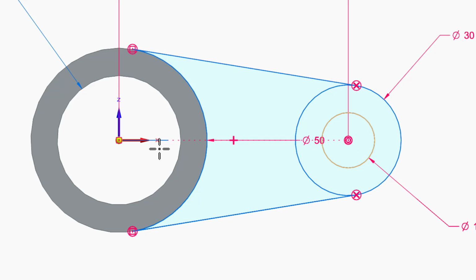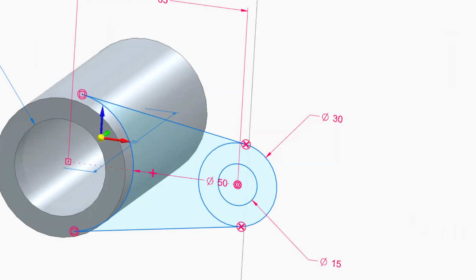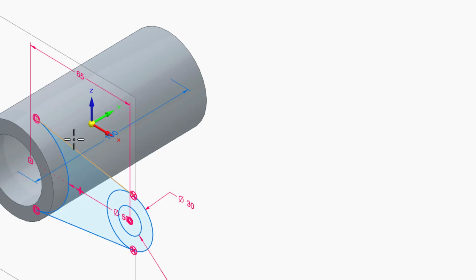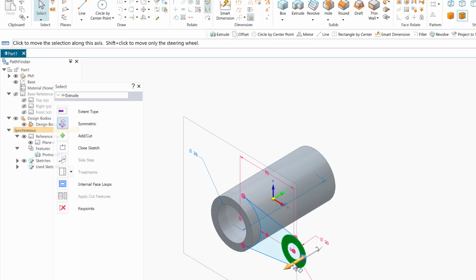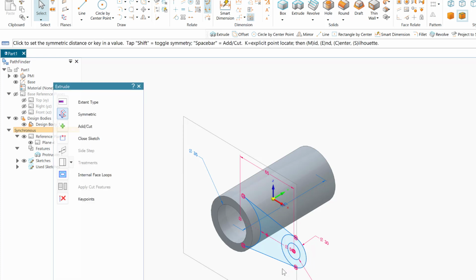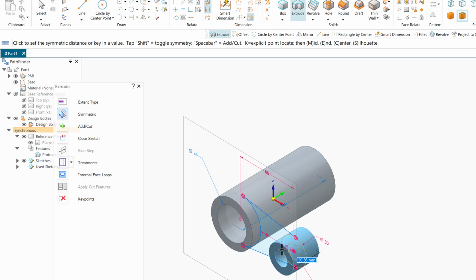So I need to do the extrusion here. So what I'm gonna do is go to home here, as you can see. Now we're gonna use the symmetric extrusion, which I can do also by the select command. So I'll get the select, click on this circle here, or this face, and use move symmetry, and how much? This one is going to be 16. I'm going to put 16,